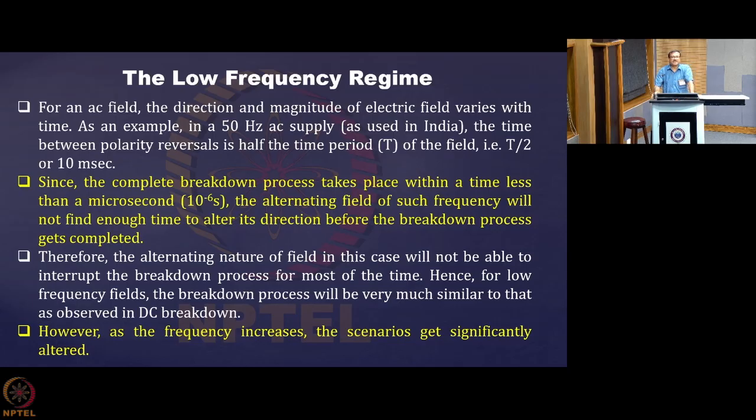Therefore, the alternating nature of the field in this case will not be able to interrupt the breakdown process most of the time. Hence, for low frequency fields, the breakdown process will be very much similar to the breakdown mechanism which we have observed in case of DC breakdown. So, as the frequency increases, the scenario will change.